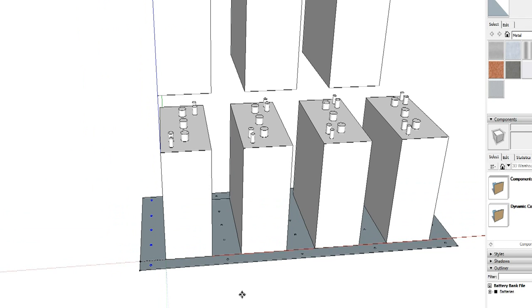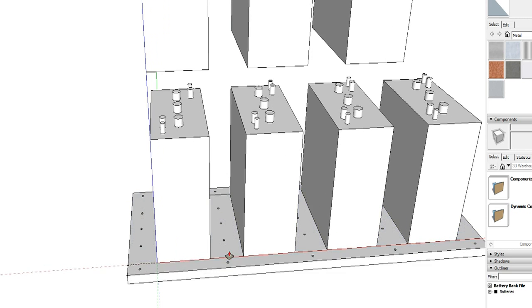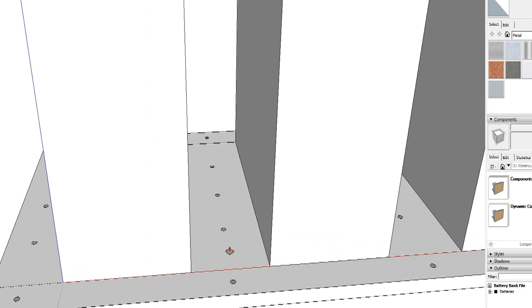Now what SketchUp tends to do when you create a sketch is to create a surface alongside it. We don't want a surface, we want a solid, and we want a solid with holes in. So what this means is when we press P, which is our pad tool, which is to extrude, and we extrude downwards, we have some surfaces there that we don't want, like these hole surfaces that we created. So mine's going to be a 2mm galvanized sheet metal plate.